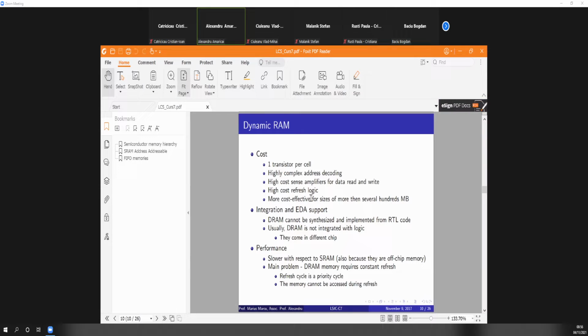It's not okay to go with a 1 megahertz frequency if the lower limit of the DRAM is 10 megahertz. Do you know why you have problems if you go with a very low frequency for the DRAM? The data becomes corrupted. Why do you think it happens?